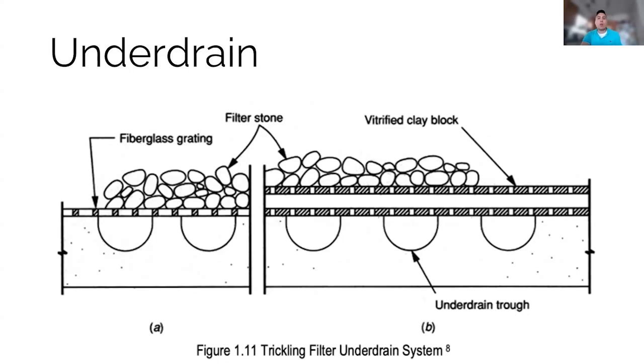One thing to point out, though, is that these underdrains can be large and hazardous, and sometimes they do need to have maintenance. So these will be considered a confined space. And so for safety precautions, you want to make sure that you treat them as a confined space and that when you are addressing them, that they're locked out and tagged out.